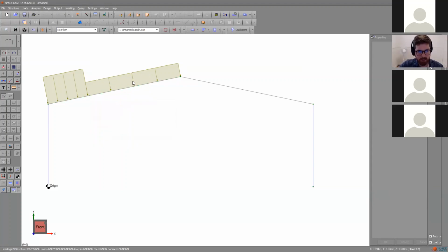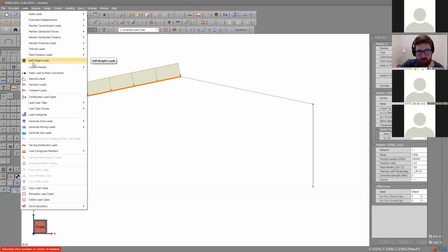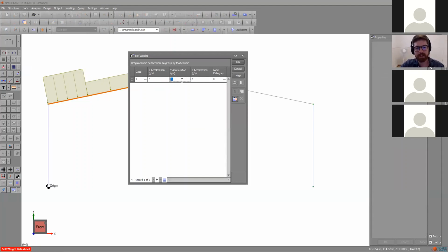Local system makes it perpendicular to the element, and then you can control the start and stop locations using the subloads to apply multiple loads to the same member. If you then also had self-weight, you can input that as a member distributed load as well. The problem there is if you change your section size, you have to change your load inputs. So to put in things like self-weights, it's probably better to use the actual self-weight load module, which automatically calculates a downwards member UDL in the global system, or at least, sorry, pointing in the direction of gravity, so -1g.